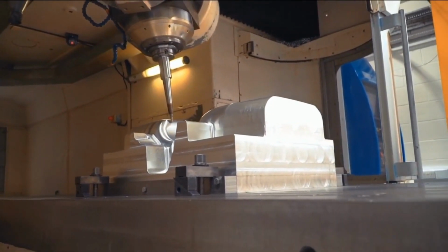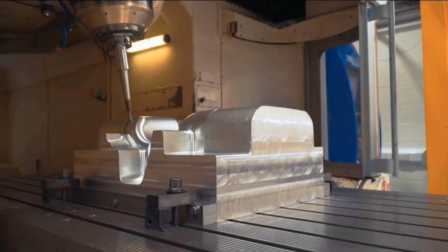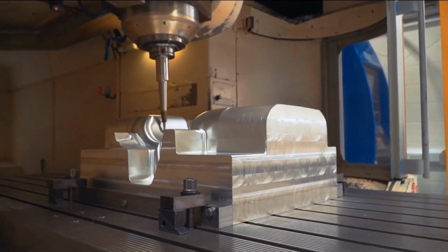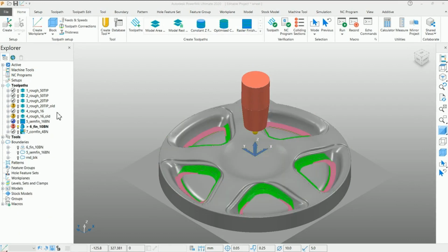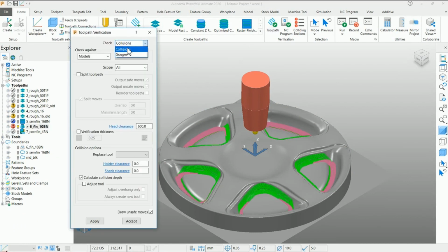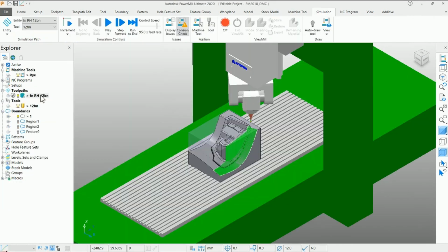Autodesk PowerMill 5-axis toolpath produces a higher level of safety for both the machine and the part. The level of safety highlights to the user where to take action, and that can be modified locally with the interactive features. Toolpath verification provides the exact value of tool overhang required with holder clearance specified by the user, and then PowerMill automatically adjusts the tool overhang to avoid holder collisions.